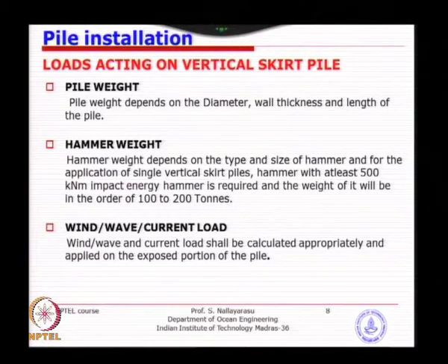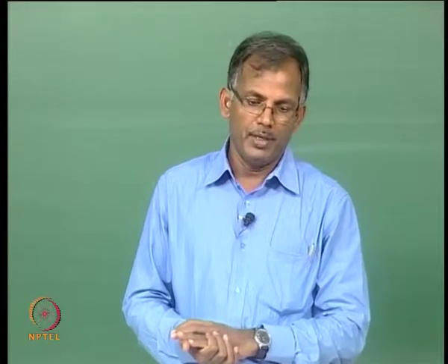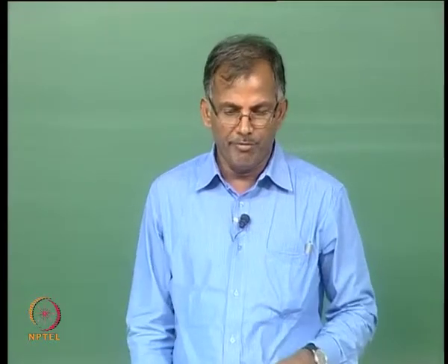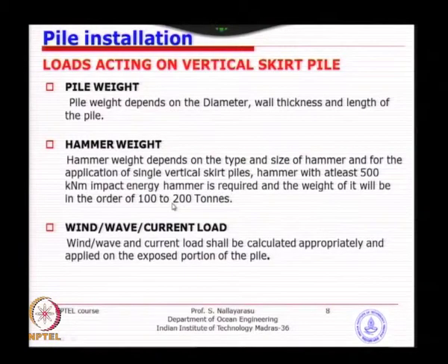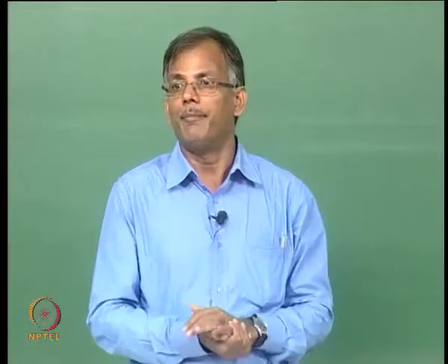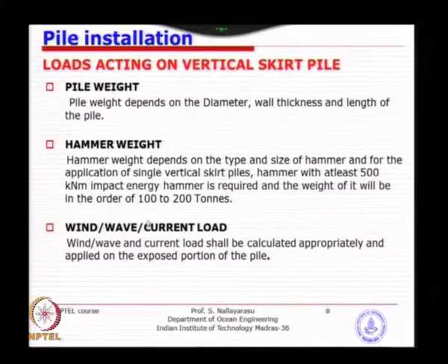If it is an inclined pile, that weight is going to be creating a large bending moment, and we have wave, wind and current loads depending on. For a main pile, you really have no worries, because the pile has gone inside the leg itself. So, it is not at all subjected to any environmental conditions, except the sticking portion, some wind load will be there. Whereas, for skirt piles, either the inclined skirt pile or the vertical skirt pile, you will have some amount of load from wave and current, but the vertical skirt pile is more vulnerable because of the cantilever in nature, no supports are provided.